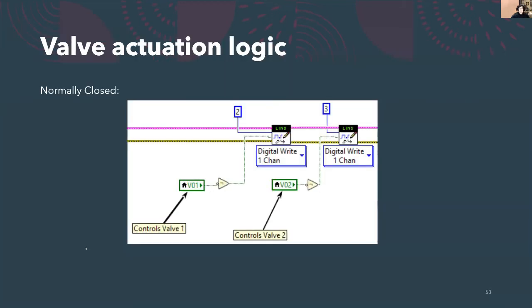Here we can take a better look at how valves 1, 2, and 4 actuate. They are normally closed valves which are controlled by 3 different buttons. These buttons only hold 2 positions, true or false. The logic gate each button feeds into is a NOT gate. This inverts the value and then sends that value to a corresponding output pin. The NOT gate is put into place to standardize how the system operates.